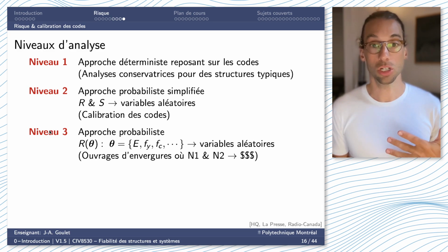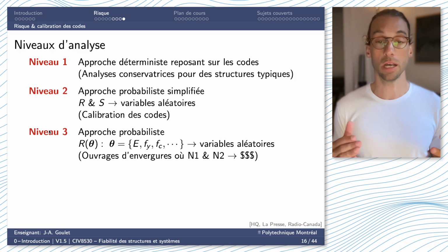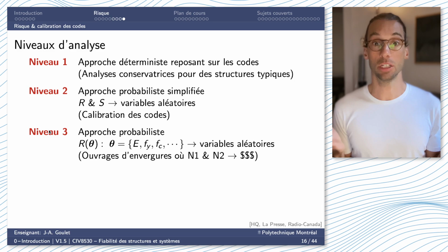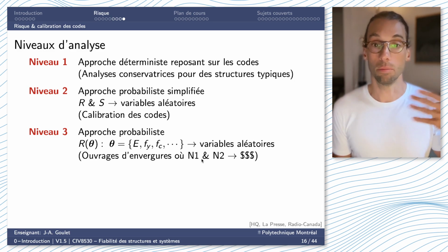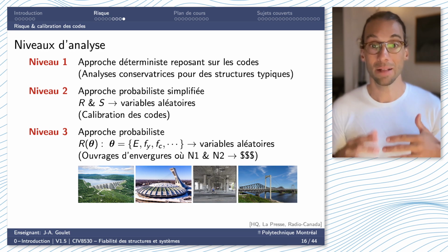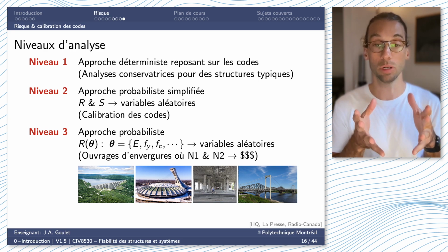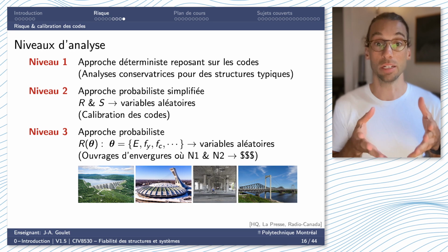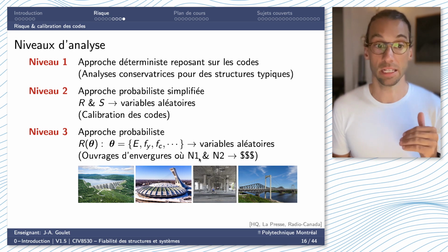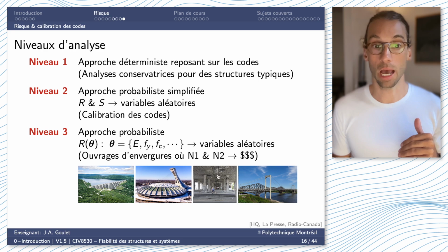So obviously such a level 3 analysis is not going to be done for any type of everyday structure. It is going to be done for much bigger structures, where the cost or the value of the structures themselves will justify the engineering time required to perform such advanced analysis, whether it is a large dam, a very intrinsically complex structure, such as here the rooftop of our Olympic Stadium. This is the Metropolitan Highway that crosses Montreal, or these are the large bridges in the region of Quebec City.